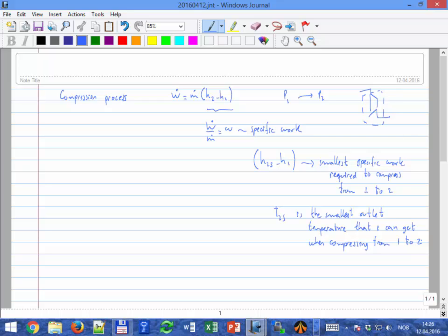And remember, some of the constraints that we listed last time was that the temperature has to be below a certain value because of the integrity of the pipelines, because of the seals of the compressor, and because if we have MEG injection, we don't want to evaporate the MEG. The MEG has a vaporization temperature of 150 degrees Celsius, more or less. If we go more than that, then it's not making it function.